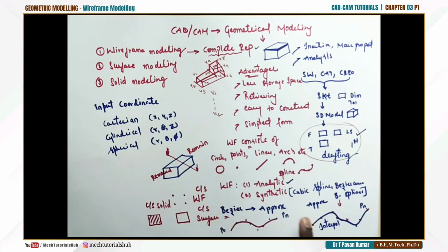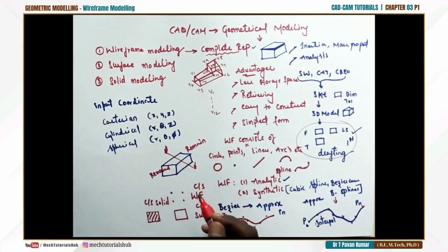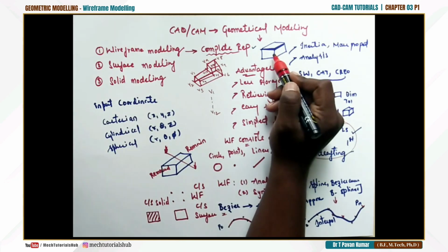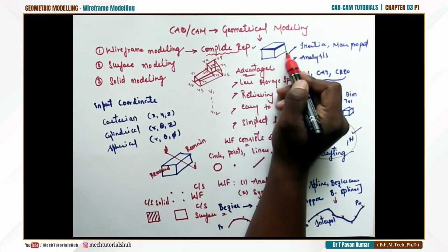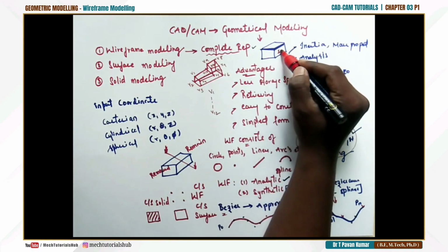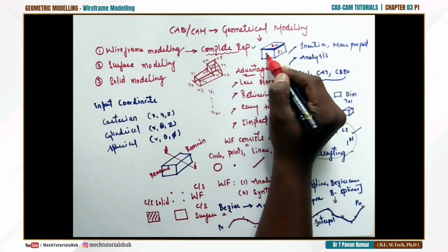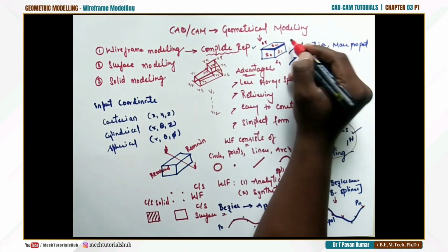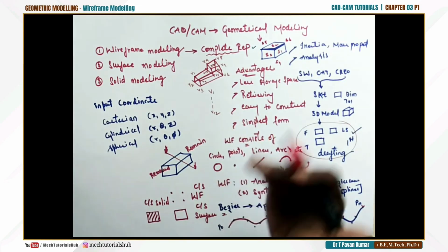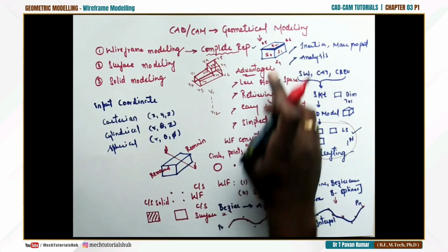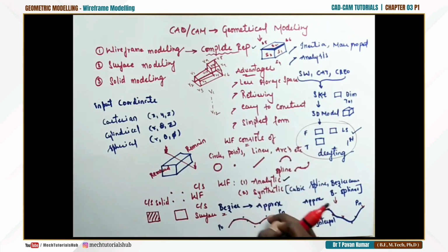Again, now this is the most important thing, approximation curve and interpolation curve. Now coming to surface modeling, consider a box. This box has to be created in surface modeling by different faces. I'll consider this as surface 1, this as surface 2, surface 3, and the bottom one surface 4, left side one surface 5, back side surface 6. If I construct 6 surfaces of the same size, I could arrive at this particular model.